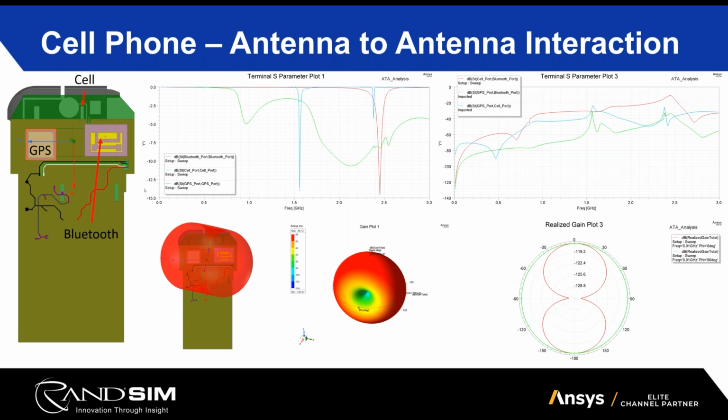So first and foremost, we want to make sure that each individual radiation pattern is sufficient to what we'd expect. So we want to make sure that the gain at varying frequencies is good enough, and that the incorporation of other things within our structure, whether that be antennas, batteries, enclosures, the actual PCB itself, the human body, if it's going to be placed up against the body, all of those things are going to impact the gain and radiation pattern of the antenna. So understanding how that's going to work truly inside of your system is very important.